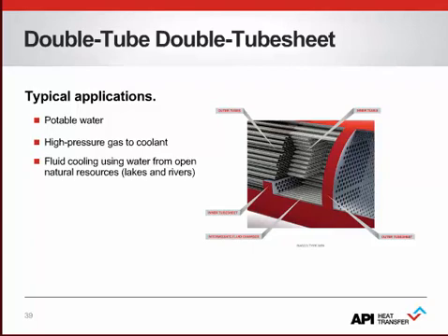Some typical applications that might require the added leak protection are those that include potable water, for example, where maybe a water source is repurposed as a heating or cooling medium, or a high-pressure flammable gas against a glycol for a cooling or preheating application. This is a case where any gas that leaks into the glycol could pose a fire or explosion hazard in